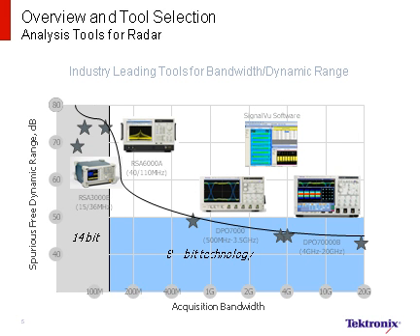In addition, our oscilloscopes have the highest instantaneous bandwidth and the greatest effective number of bits for doing measurements. Models are available to 20 gigahertz in bandwidth, enabling you to directly capture Ku band radar signals without the need for additional down conversion or time-consuming calibration procedures. When combined with the SignalVu software, our oscilloscopes mirror the functionality and analysis of high-performance spectrum analyzers, and the capabilities discussed in this webinar are available across all of our spectrum analyzers and real-time oscilloscope platforms, and they can replace the myriad of test equipment historically used to test radar signals.